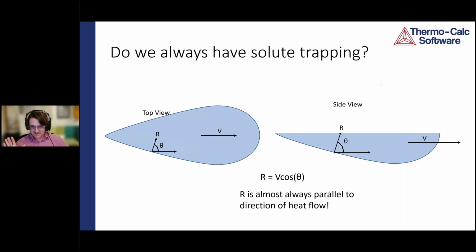One thing that's missed by many, I think, is that the solidification velocity is not the travel speed. Okay, so I'm a welding engineer, so I'm going to say travel speed and not raster speed, but the laser is moving, the melt pool is moving, right, in the steady state at the velocity that we're rastering the laser. So let's say we're rastering the laser at 1 meter per second. Okay, so that's our V. V equals 1 meter per second.